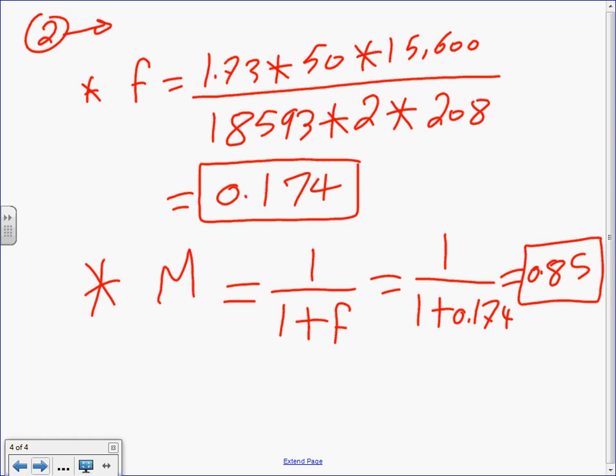Guys, NEC 2011 requires all service entrance panels to have a short circuit rating. That's as of 2011. What does that mean to you and your company? Means you guys are going to be doing this calculation, or you're going to hire an engineer to do the calculation. There are two ways of doing it. If you don't have SKM, which you have to pay close to $10,000 to $40,000 to have for your company, there is a method that you can do an approximate value by hand. Cool?